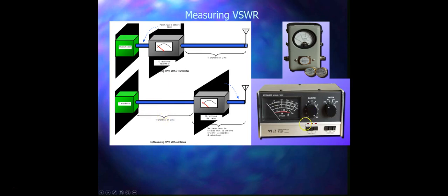And these are real directional wattmeters which you can use. There is an option called sensor select here, and this is the power range which you can select. First, if you want to use this directional wattmeter, you click on the sensor select button corresponding to the system under test.